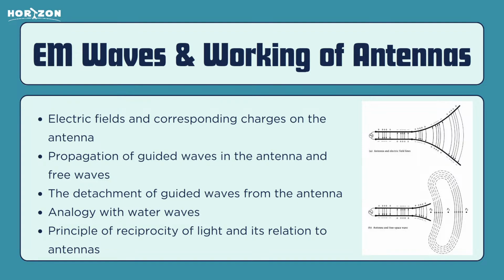Another thing to note in the second diagram is the connections between the open ends of the electric field lines, which is indicated with a dashed line. When the electromagnetic waves are within the transmission line and the antenna, they are associated with charges in the conductors. However, when the waves are radiated, they form closed loops without charges to sustain them.